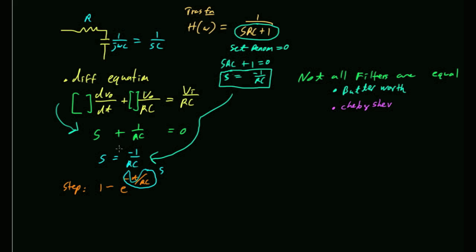Yes? Yes, absolutely. And the only reason I do that is that if I don't, when I get to more sophisticated circuits that have, let's say, an inductor and a capacitor, or 2 capacitors, then people start to panic. If they have 2 j omega terms and they multiply them against each other, they're like, oh, that's equal to minus omega squared, which is true. It just makes the math ugly as anything. So instead, you just leave it as s's, and then they're easy to multiply together.